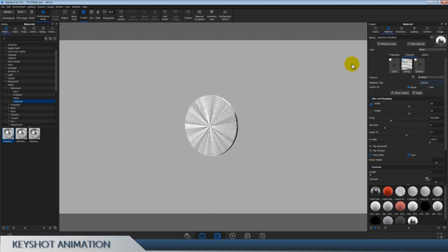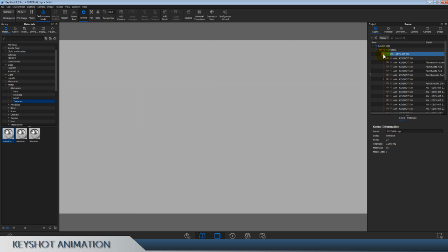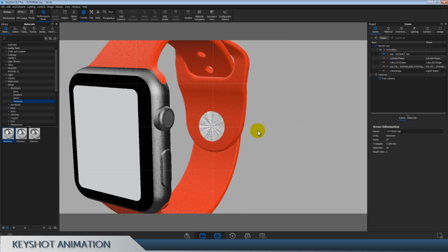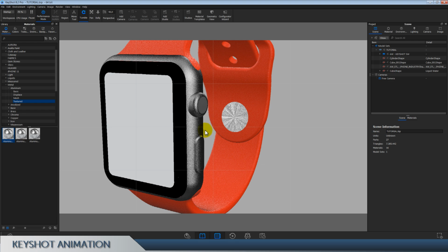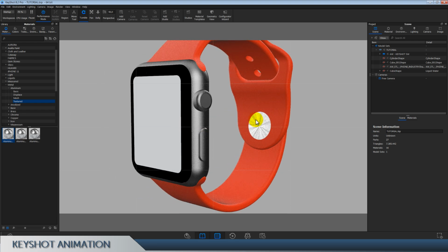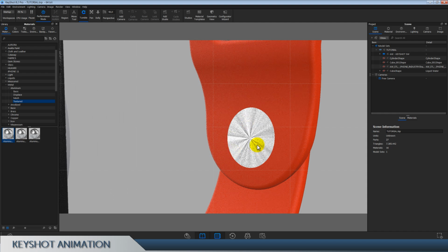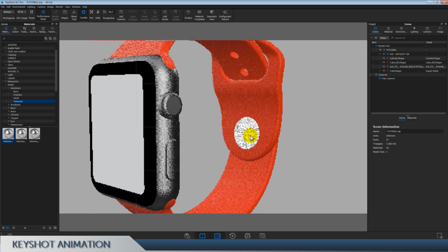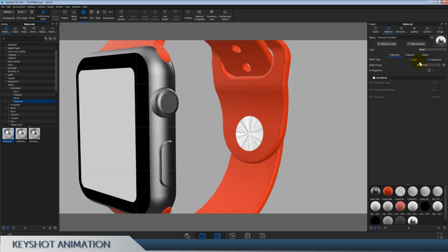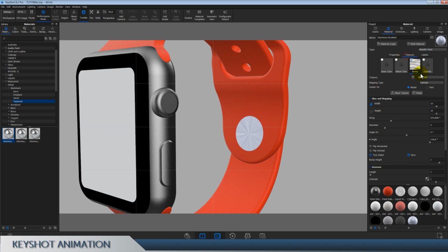Now when you have that done, I'm gonna switch off and unhide our parts. As you can see, it's not really matching our metal color, so let's see what we have to do. Also, I think it has too much of these. Let's try to simplify. I'm gonna switch material from metal to metallic paint. You can see already a huge change. And for the base color, I'm gonna click on bump, hold shift and move bump to base color as well. Again, you can see another change.